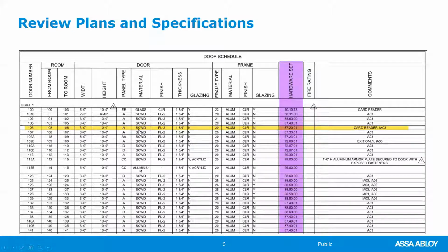The door elevation, is it a solid flush wood door? Is it a metal door, fiberglass, aluminum? What type of material and what type of elevation? Is there any glass in the door? Does that glass possibly interfere with an exit device or a lock set? And what is the style and rail dimensions? Do you possibly need drop plates on door closers? Items like that that you're paying attention to.